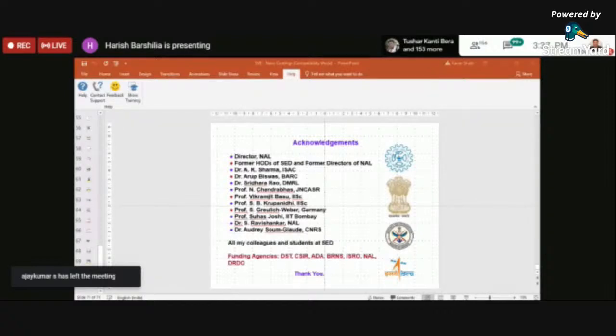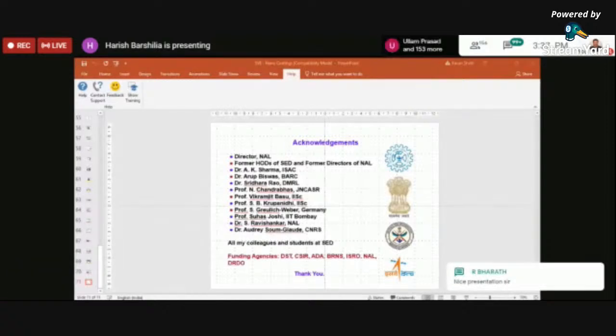But also one important thing is that whenever you are talking about the thermal barrier coating, the thermal conductivity has to be as low as possible, because inside the turbine, if the temperature is say 1500 degrees Celsius, and the enclosure, even if it is stable, has a very high thermal conductivity, the heat will get dissipated outside, so you will not be able to maintain that temperature.